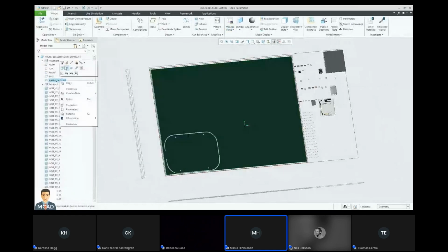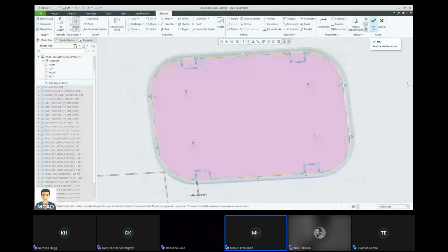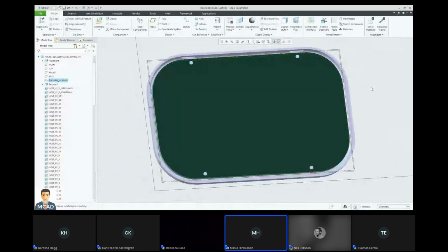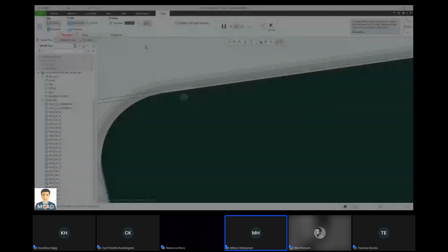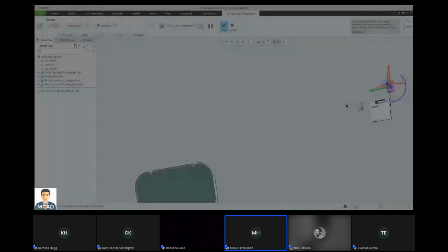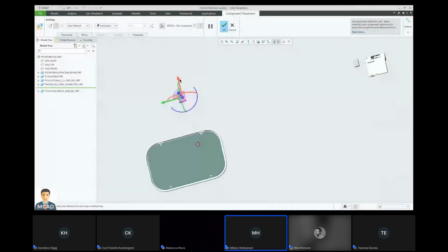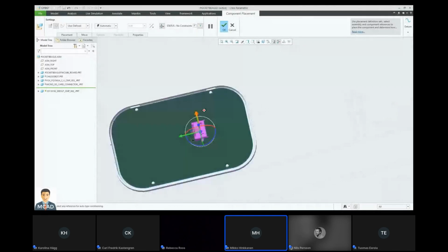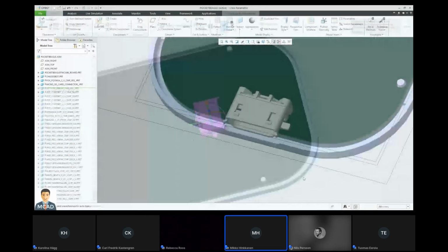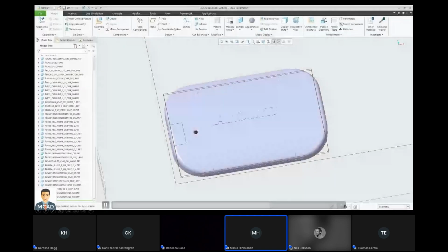and just place it on his mechanical design and start manipulating the design so that it will fit the purpose. So the first thing to do is, of course, manipulate the board layout so that it actually will fit in the enclosure room. Using just basic modeling operations, we will now make sure that we are able to make the board holes in there, and that the general form, fit, and function suit the board size and shape. And then we simply drag the models and place them on the PCB board so that mechanically the design is valid without really consulting any of the electronic design, but something that makes sense in the mechanical world.